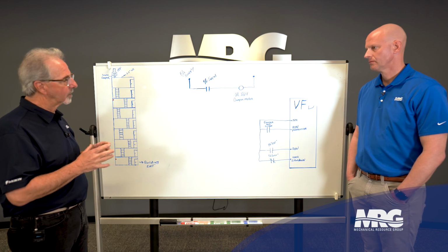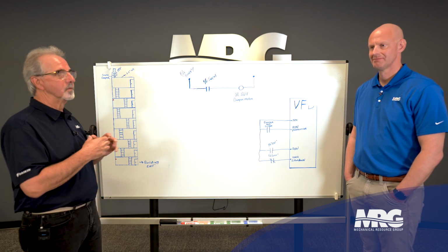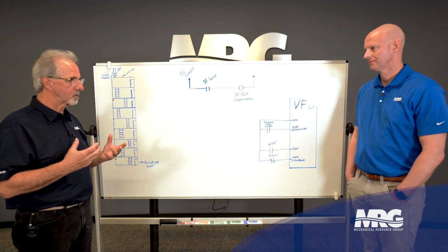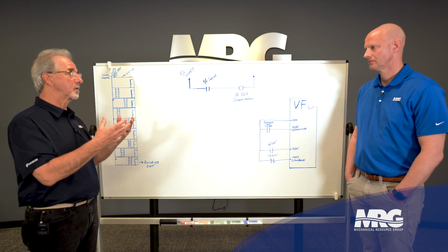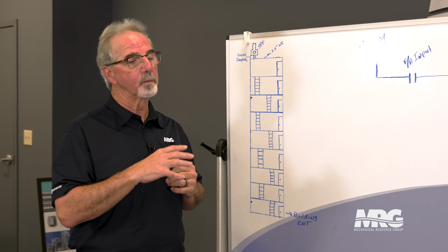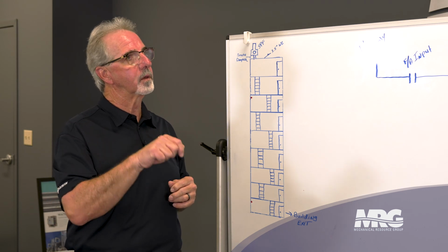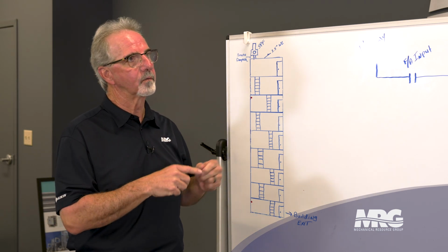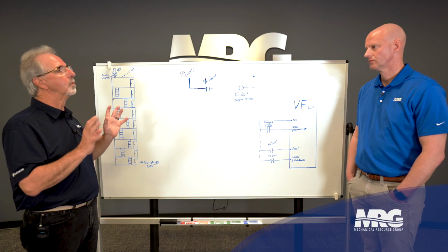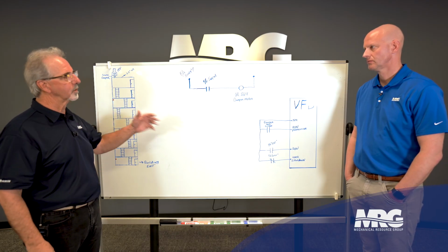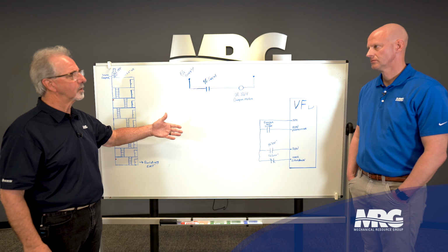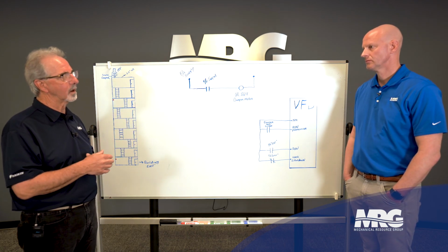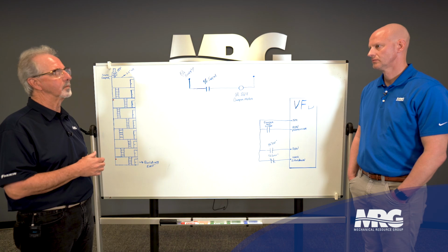Gotcha. One other thing that I do want to touch on is that when we get this hand-off in some applications where it's stairwell pressurization, or if it's a return fan with exhaust, sometimes what happens is fire alarm with a key switch can come in there and they can turn that switch, and all of these devices will run to destruction. It won't respond to a circuit breaker trip, won't respond to an overload. If we overload the drive, it's not going to trip. It runs to destruction, and that's usually on an election by the fire department on site.